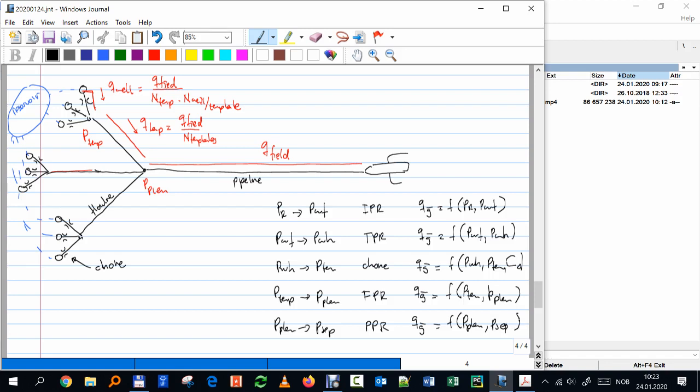So that's all. We are going to neglect temperature for now. We are looking simply at pressure, because we know pressure represents energy. Also temperature represents energy, but we will say pressure, and we want two pressure nodes, and we have to see how much is going to be lost from the reservoir all the way to the separator. If that energy balance is positive, that means I can produce the rate. If that energy balance is negative, that means I cannot produce the rate. In a kind of simplistic way.